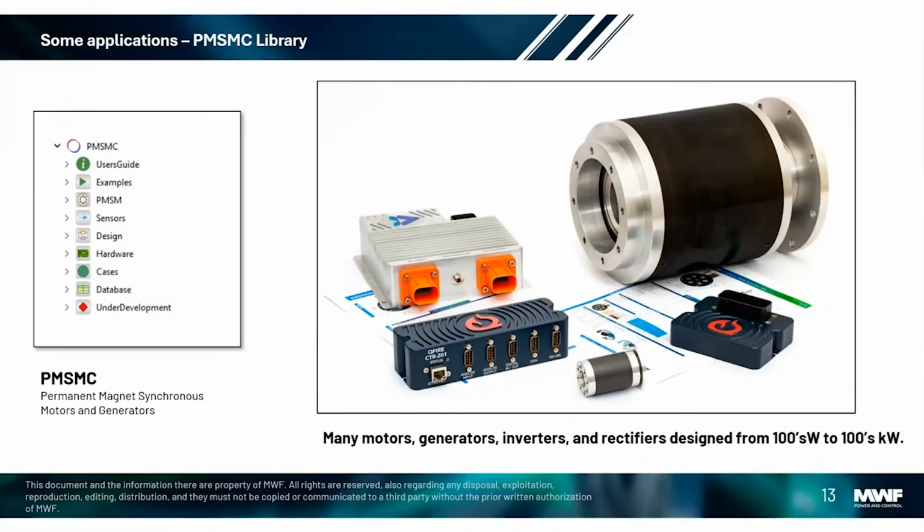As you can see in this picture, we have some motors which were designed based on this library, and some inverters and controllers that at some point have also had details verified in this library in many different aspects, like for example the details about the gate drivers, about the SVPWM modulation, the magnetic and thermal characteristics of the motors, and so on.